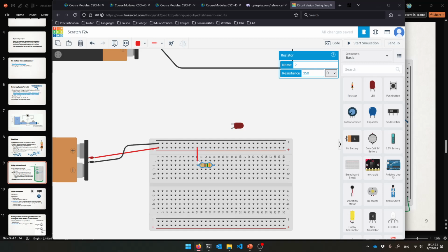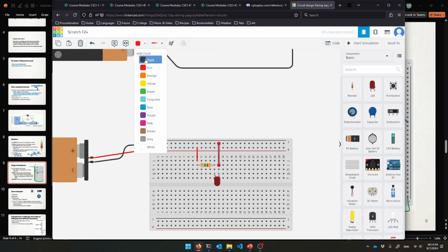So positive's coming in to here, resisted across to here, so now I can hook into any of these. I'll hook in this LED and turn it a little because I need positive going into the anode. Now we've got power coming in this way, flowing out through the cathode down to hopefully negative, and that should be a black wire, right?